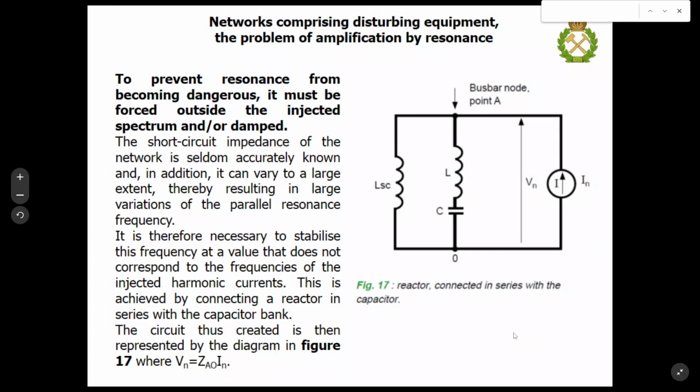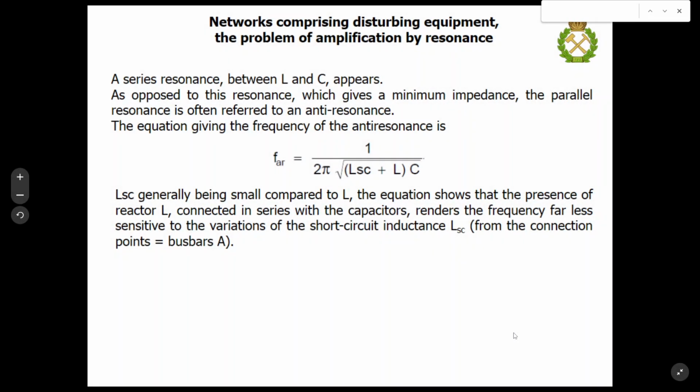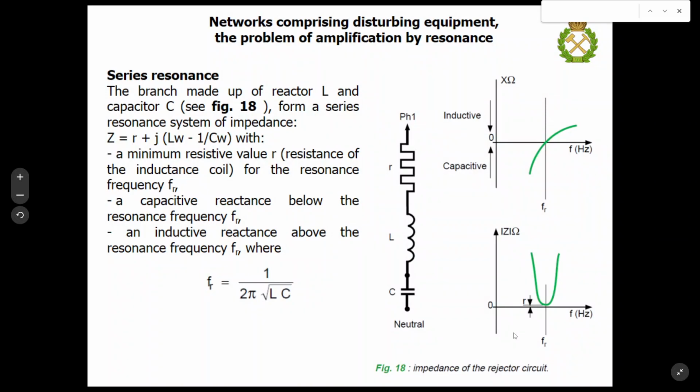And also we should take into account technical devices to prevent resonance, for example, filter devices. Such filters can be based on series resonance or shunt resonance, when we use active, inductive, and capacitance filters, which have the resonance frequency according to this equation.